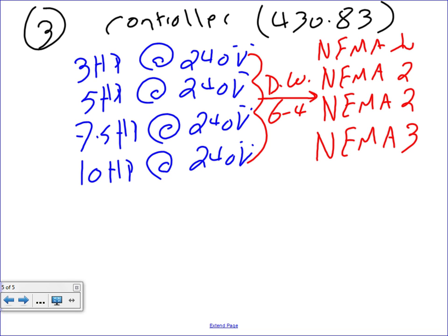Why do you say NEMA 1, NEMA 2, NEMA 3? Because if you look at the top here, it says NEMA ratings for AC starters in ampere, horsepower, phase, and voltage. Where did you get NEMA 3? NEMA 3 is up to, I need 10 horsepower, so what's my next standard? My next one can go all the way up to 50. It's confusing. Jackson understood it better and he showed it to me. I believe other people are confused. You've got to let them know how to trace it to the NEMA rating. So that's what they are asking.